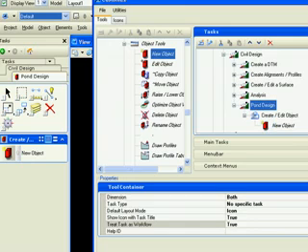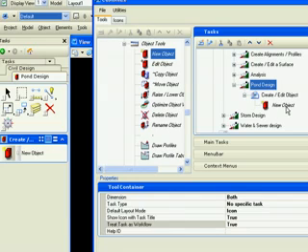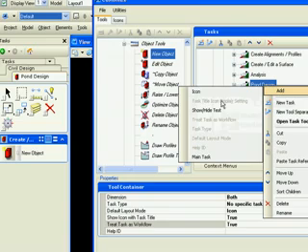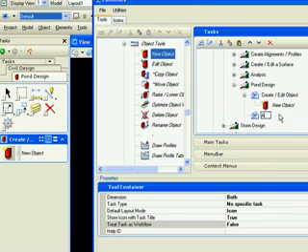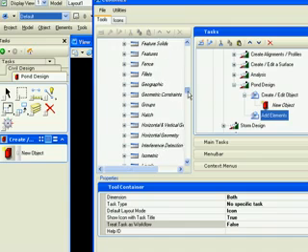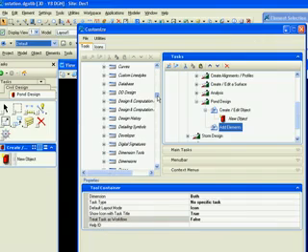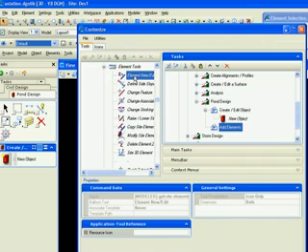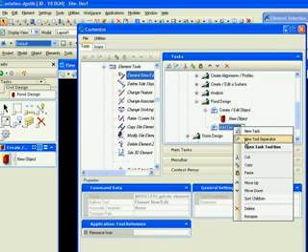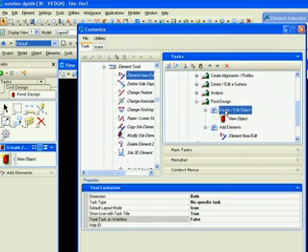The next thing I want to do is add elements to that object. So again, I'll add a new task, and now we'll go and add elements. Again, if Site Modeler is not open, these Site Modeler tools will not be available to you. So we'll copy and paste. Now up here in our create edit object, I may also want to place my edit object.